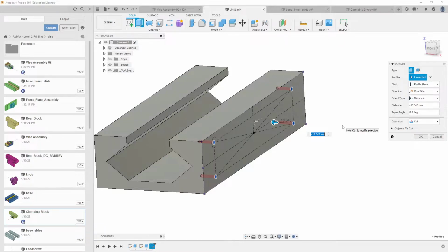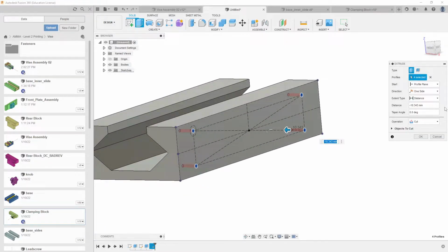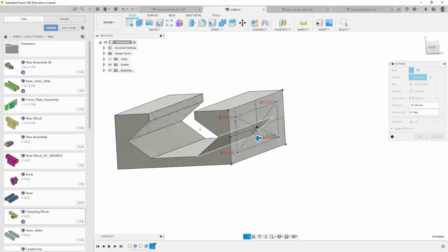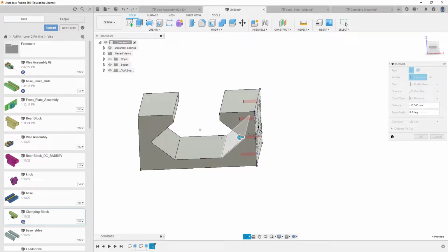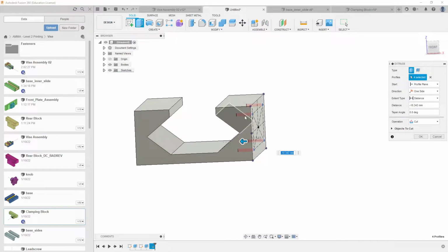So if you want to give that a shot, you could. You know what? I'm going to call an audible as I'm doing this. I'm going to go ahead and make this, so you look in the side here. How far in do you want this hole to go? 10 seems sufficient, so I'll have to remember that we got 10 on this side, and then maybe 10 on the other side for a 20mm fastener. By the way, hold on to that thought. I didn't mean to sound like it's an afterthought. It's a big deal. We have our 16mm fasteners, 20, we've got 25, we've got 30mm fasteners, so we have to be aware of that fact.